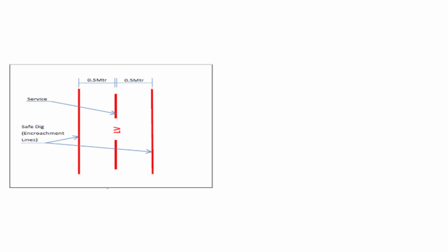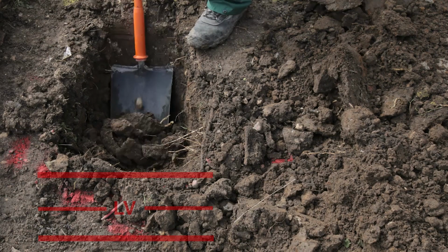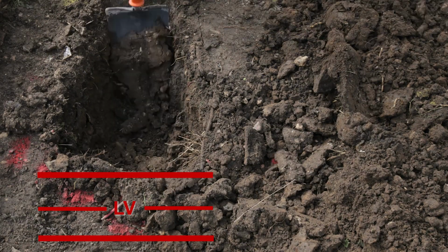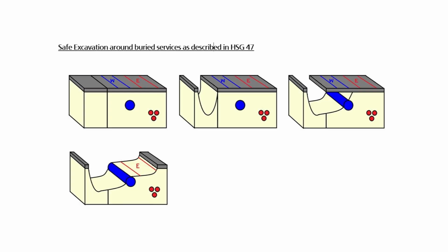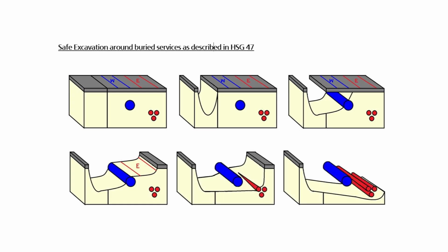When excavating, it is important to adhere to the minimum safe excavation distances. Exclusion zones must be adhered to when breaking out the top layer of tarmac and wearing course. Once a section of this has been removed, hand digging should start outside the exclusion zones, then moving steadily in, undermining and safely exposing buried assets.